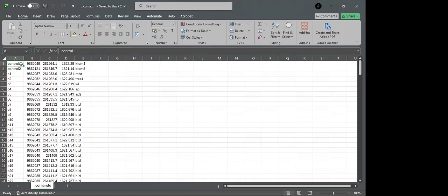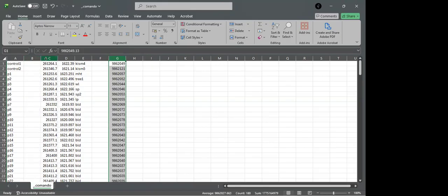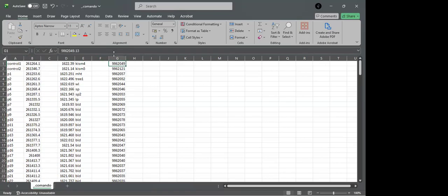I can discard all this data, just have it in numeric, or rather, I can just retain it. I know the issue I'm having here is this is the northing. I'm going to cut it, paste it here, and then move the easting so that we have the easting coming first, followed by the northing, then the elevation.